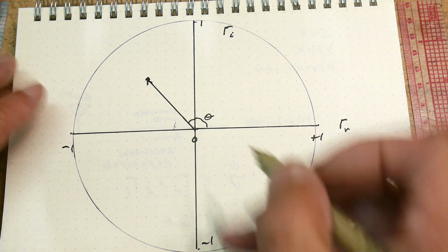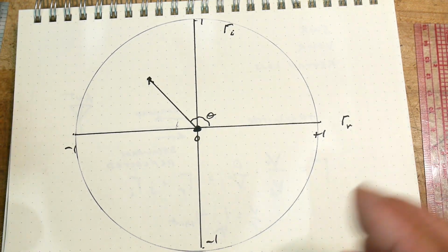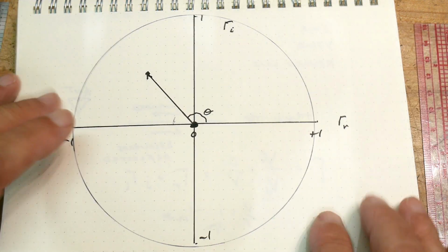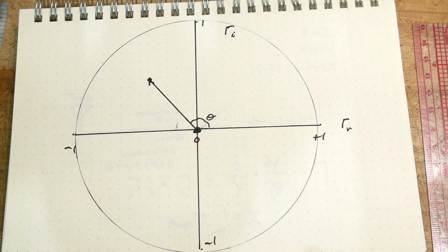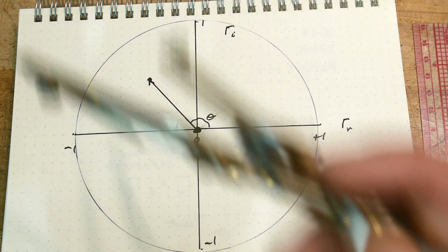And what does this mean? Well, it means that here's the goodness, right? That center point is when everything is perfect. Remember, gamma is volts over volts, and when it's 0, then everything is perfect, everything is matched. And anytime you move away from the center, you have a mismatch, okay? Well, what's a mismatch? Mismatch can be called return loss. It can be called VSWR. It can be called lots of things, and here we're calling it gamma, or the reflection coefficient, right? All right. So what does it mean to be goodness?